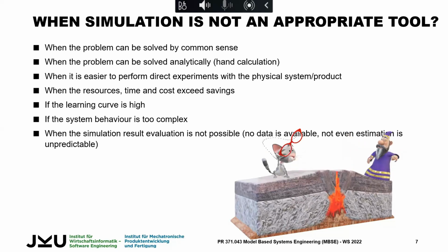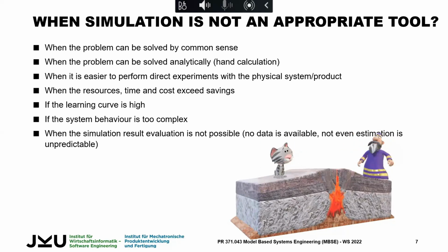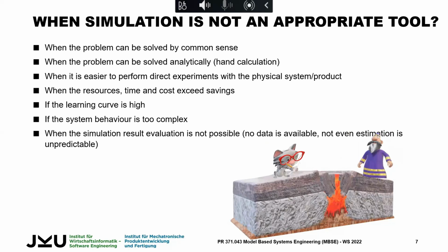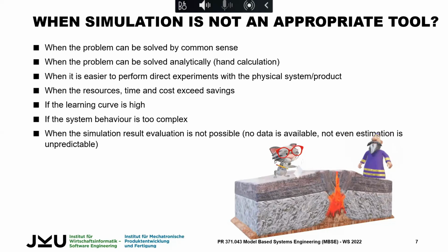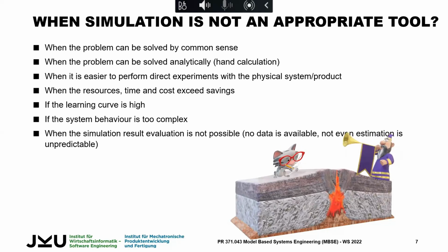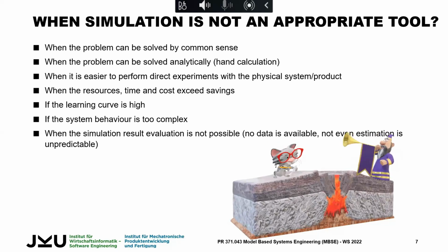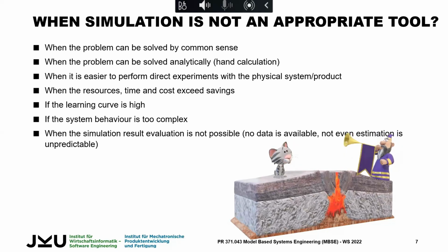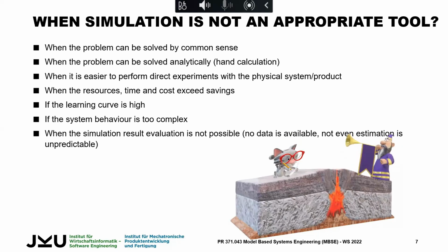You have to prove that the result you got is correct in relation to other results, or you can apply some kind of regulations. Maybe the regulations have limits, like this kind of structure with this kind of material could have this kind of stress limit. So for finite element analysis there are certain rules you will find, so there it is possible.